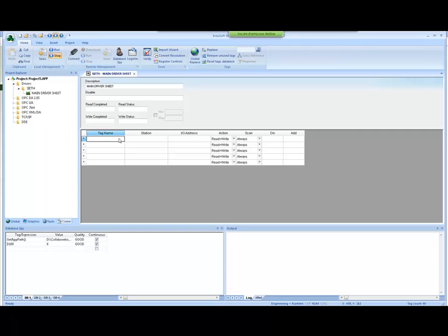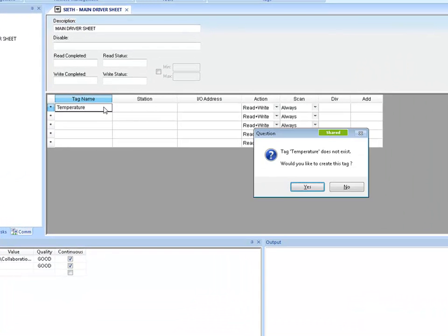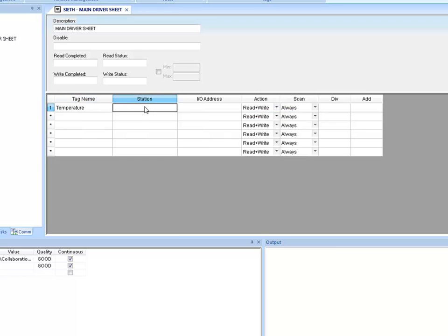one tag. So let's say that I have my temperature, and the temperature is a real tag, and that one goes to the PLC with the IP 192.168.0.99, for example. And I'm gonna go on my input word 11, for instance. I'm gonna read that as a floating point, so I put an F on it, or IF. Is that pretty much what I do?